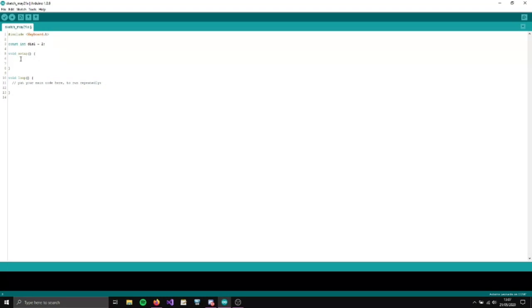Right, so in void setup, we need to determine the pin mode of dispatch1 as INPUT_PULLUP. And you might be thinking, why don't you just use INPUT? You can just use INPUT, but there's a very good reason not to, and that's because it can actually burn out your Arduino if you haven't put a resistor in between the button and your ground. Essentially, if you're not using a resistor, there's an electrical flow going out of the 5 volts on the Arduino and going straight back in with no resistance. After a while, it'll burn out your board and completely fry it. So we don't want that.